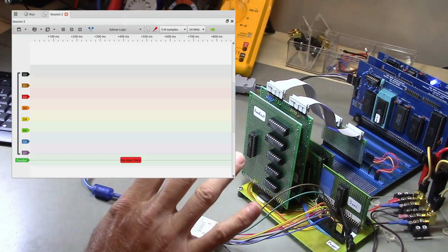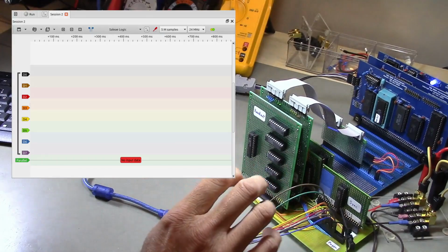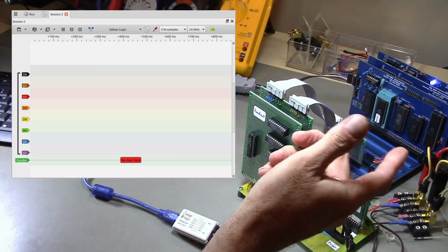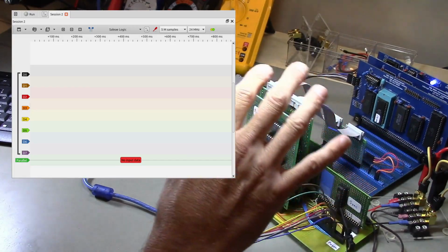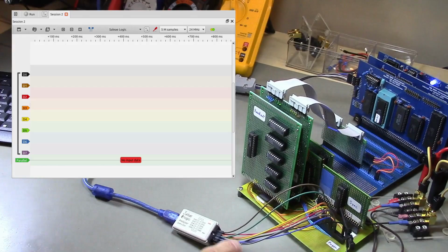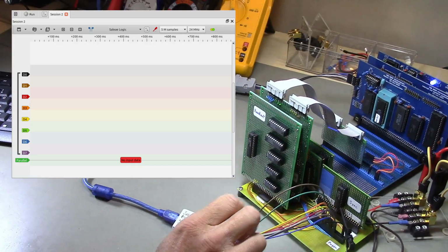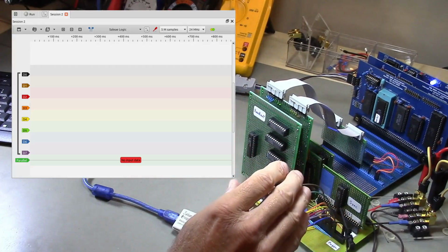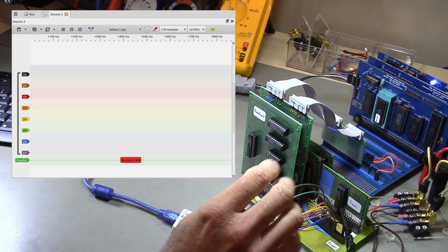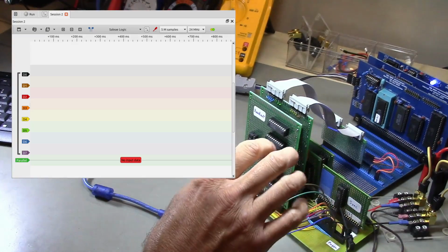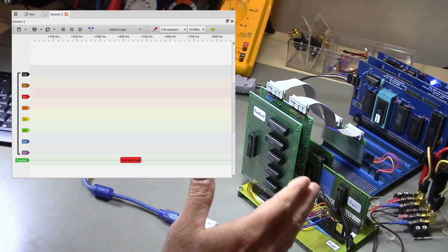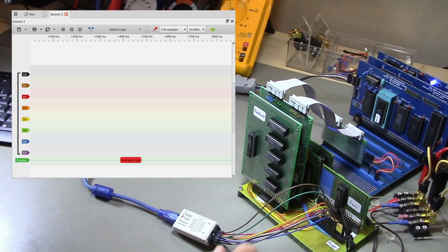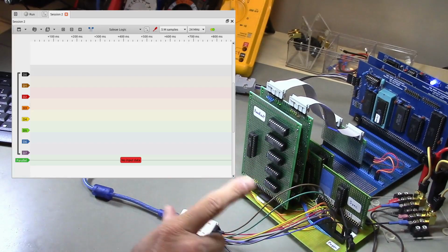So the way that the display controller talks to the VRAM is that the Readout module generates an address, and then whatever data is in the RAM should appear on the data outputs. There's no clock involved, and so we don't necessarily get absolutely consistent data values from one byte to another. So there may be intermediate states that aren't valid data. We just need the byte to be valid after 3 clock cycles so that it can be latched into a register. But in general, we should see these increasing byte values.